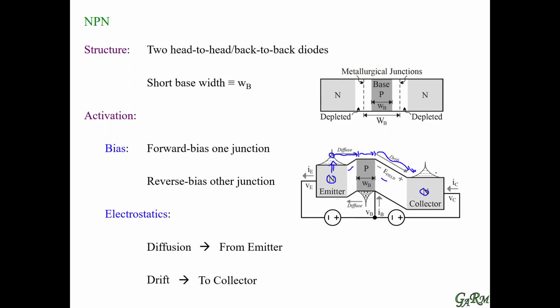The other thing is that we see charge carriers leaving the collector. And remember that current flow is in the opposite direction of electrons. So electrons leaving the collector means that there is a collector current going into the collector, and that's down here. That's the one that we're referring to with I sub C.